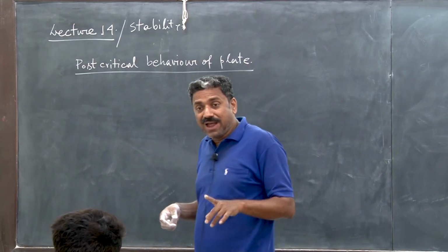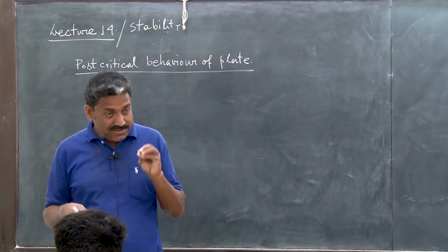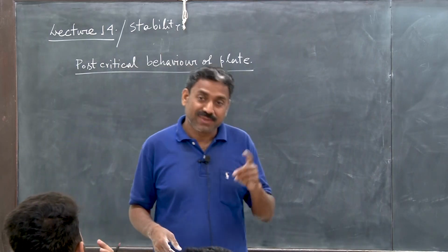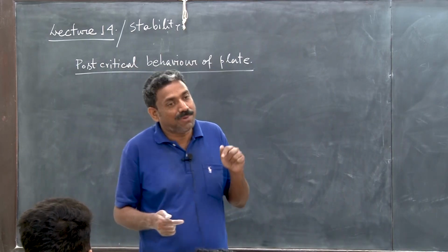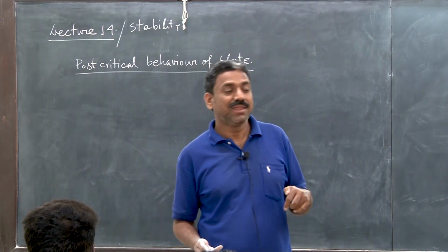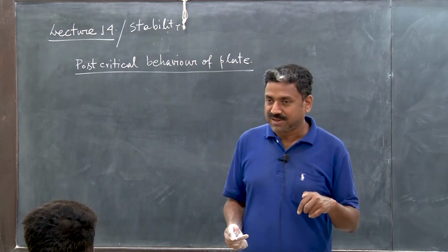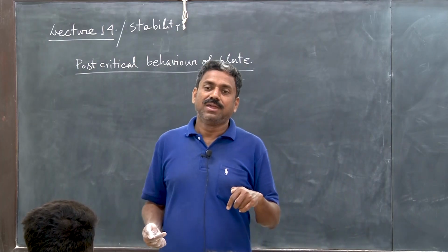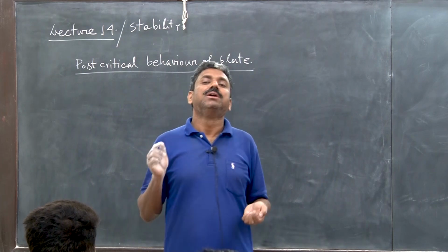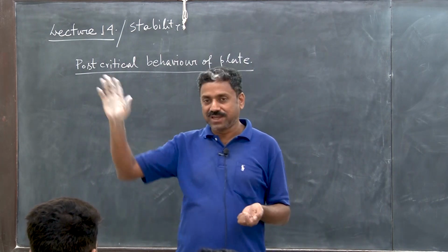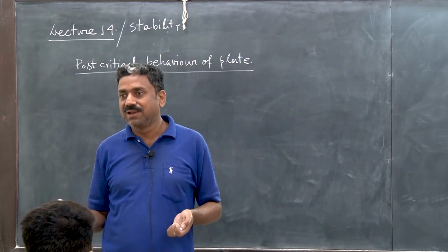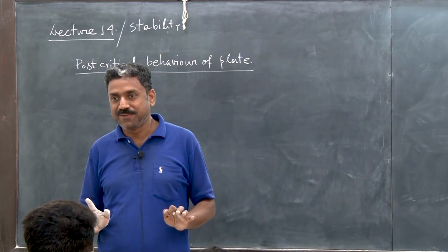Now, we have demonstrated those simple behaviors, demonstrated by the toy system, in one practical example. We have considered the buckling of a column and the post-buckling of a column. We have seen that a column does not have any significant post-buckling strength. Even if the end rotation is 30 degrees, it is only a 3 to 4% increase in post-critical capacity. So essentially, for the column, as soon as it buckles, it depletes all its load carrying capacity.